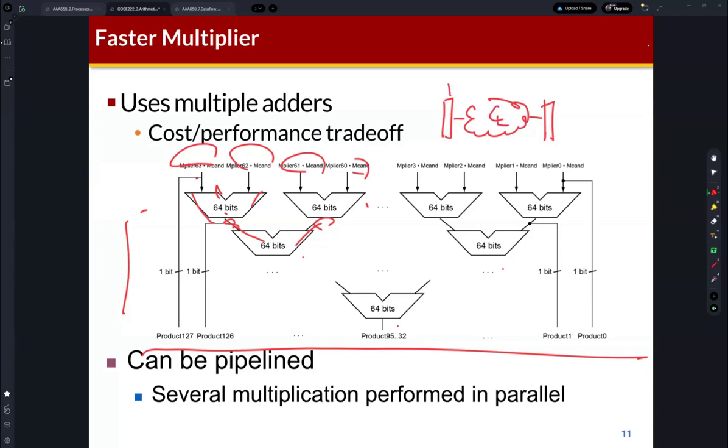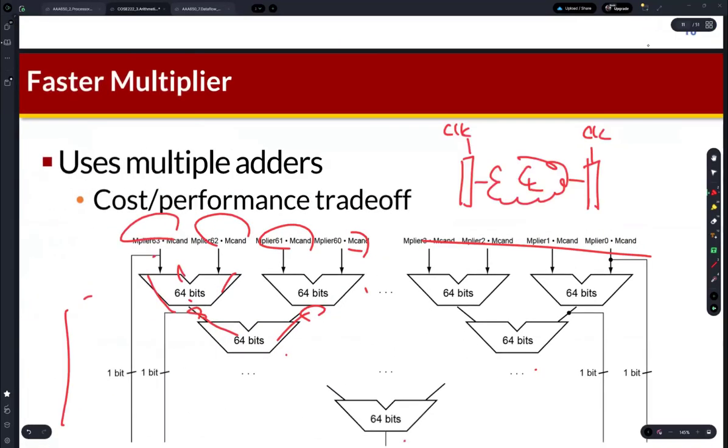This is the combination logic, and this is the D flip-flop. So a digital system can be implemented like this, right? There are flip-flops, and between these flip-flops you can find the combination logic, which is required for generating some result. The combination logic has a delay, delta t, and the clock period is determined by this delta t.